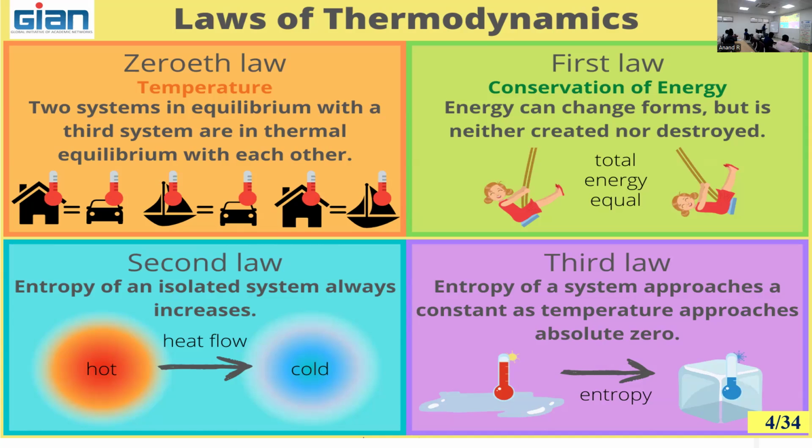Right? So then Carnot, the French scientist and army engineer, invented the cycle, which has four processes, two isentropic and two isothermal. Considering that, it is the maximum hypothetical cycle you can do. From the Carnot cycle he found the maximum efficiency. So that is the ideal efficiency. You cannot get more than that.